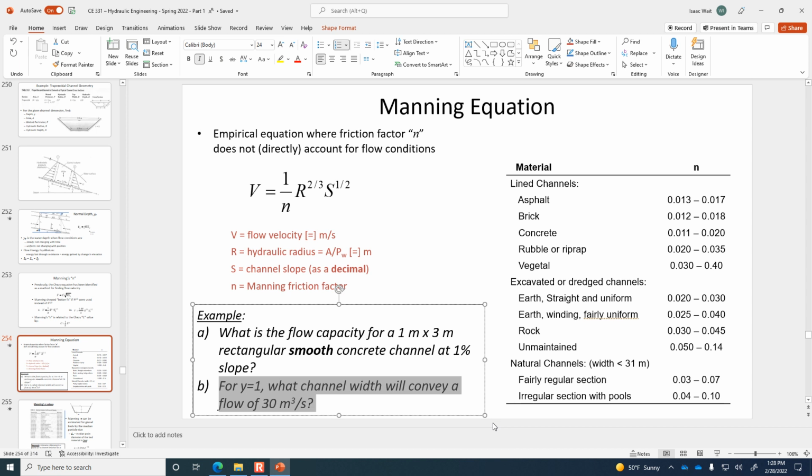All right. So here in our rectangular channel geometry, area will be B, the unknown width, times 1. That's the area. And the wetted perimeter, P, is, if we have this width and a depth of 1, it would be 2 plus B for the perimeter, because there's 1 on the left, 1 on the right, and then however wide the channel is.